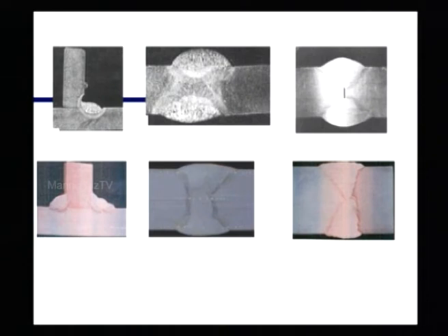You can see very common defects what we have here in the yard. One of these defects is basically undercut, and this undercut is the initiation of many other problems, like let's say cracks and so on.